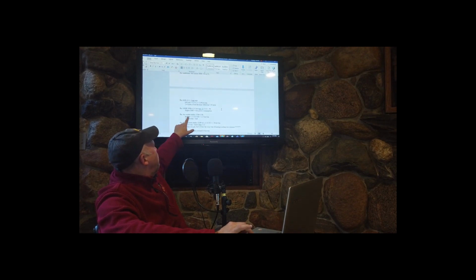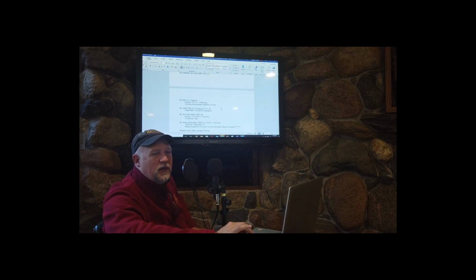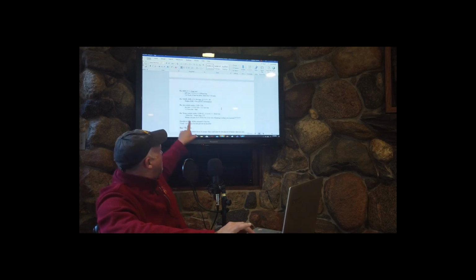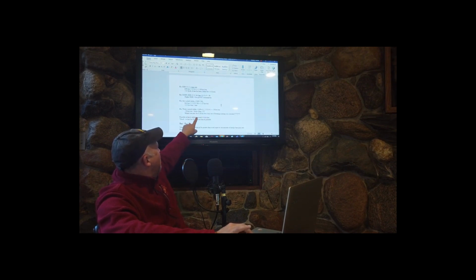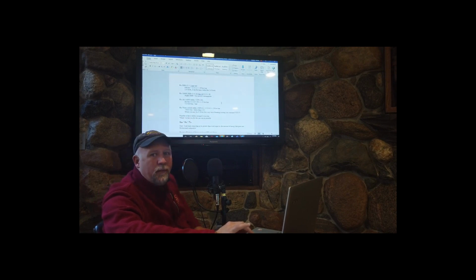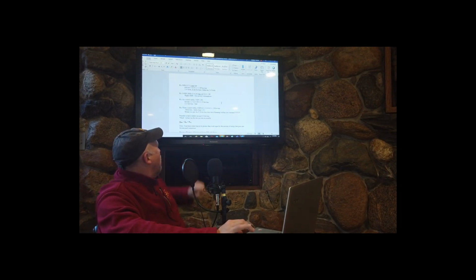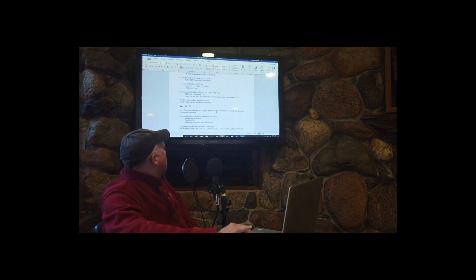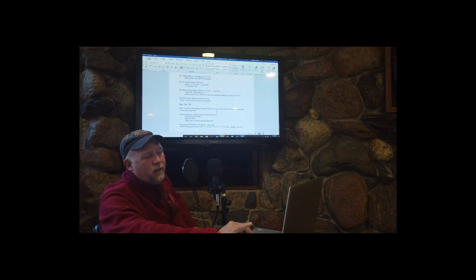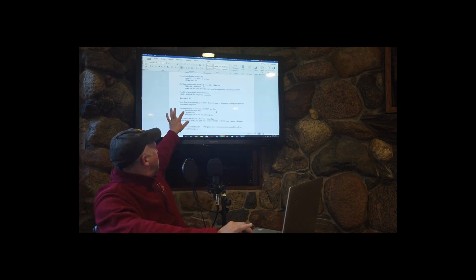An air-cooled chiller, probably down around 1.25 kilowatts per ton. Not as good as some of the other options. Look at this for the water-cooled chiller. You can get those at 0.58 kW per ton, and probably even better, some chillers are at 0.4 kW per ton and maybe even less. Like that magnetic bearing chiller is probably less than 0.4 kW per ton. Those are pretty awesome.